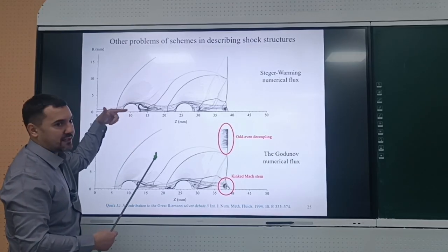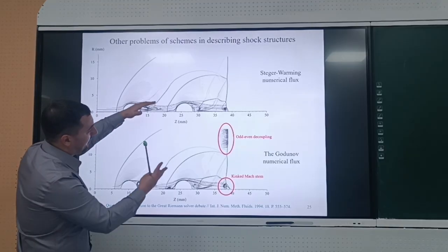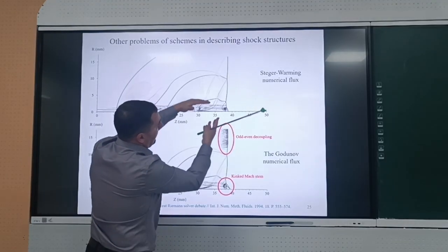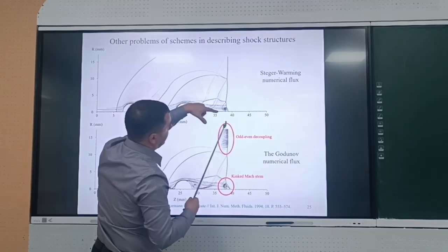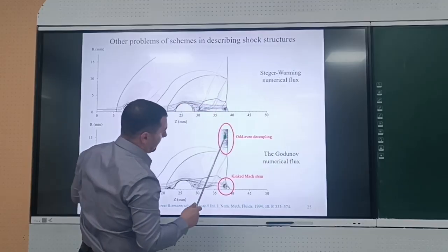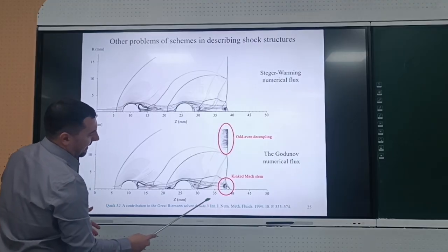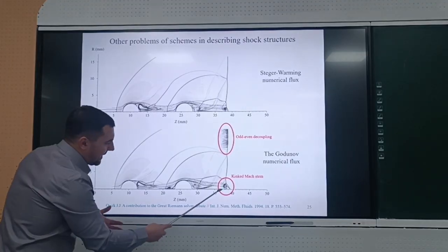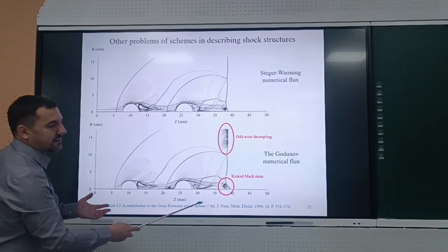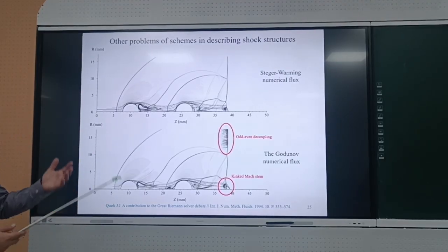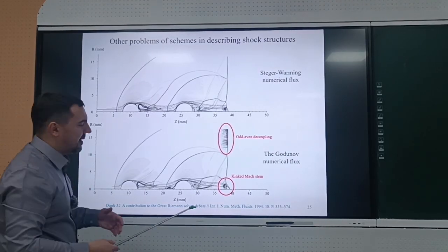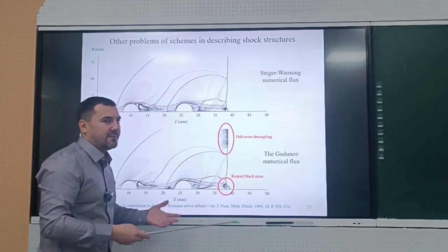So actually, they are spheres, and so you have the collision of shock waves in the wake of the cylinder, and the Mach stem should form. And here you have just the wrong picture. If you did not know about that, you might think that okay, that's a good solution, or well, for example, Fluent or I don't know what provides you with this picture. What can we do about that?